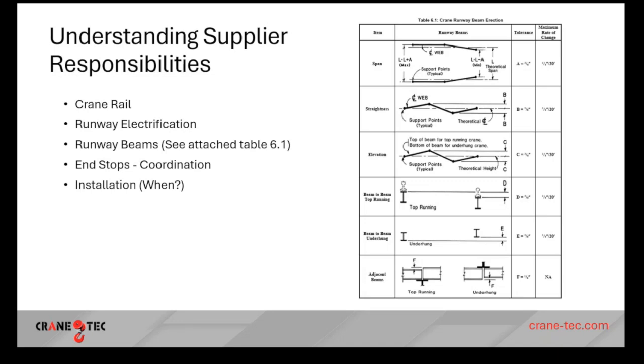So I suppose the end question would be, it's an extraordinarily tight tolerance, and I understand it for your rails. For the beams themselves, that's intended to keep the rail centered over the web of the beam, obviously. But have you seen exceptions, or who would provide the exception if you could get it to within a half an inch instead of 3/8 or something from the center of the web, because there's just no adjustment left in the building? Or has that ever happened, or is it just always held to the MBMA spec?